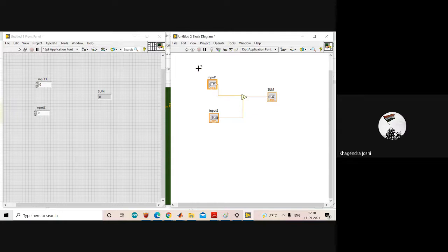Now before running it, I will show you the second procedure to mention the inputs. You can just delete whatever you want by selecting that particular portion. So this way, now some broken wires are there on the screen. The third shortcut is Control B. The moment you press Control B, all the bad wires, or I can say all the broken wires, will get removed. Right.